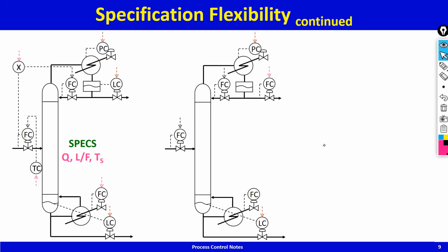That means if the flow changes a little bit, if any disturbance goes into that unit, it's very hard to stabilize it. So you don't want to unnecessarily disturb that unit. So instead of fixing the column feed, we're going to fix the feed to that fragile unit, and the feed to that fragile unit happens to be the distillate of this column. So now processing rate is being fixed at the distillate.